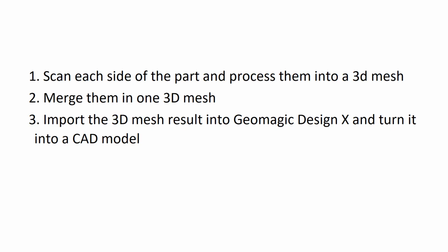So my plan is, firstly, scan each side of the part and process them into a 3D mesh. Secondly, merge them in one 3D mesh. And thirdly, import the 3D mesh result into Geometric Design X and turn it into a CAD model.